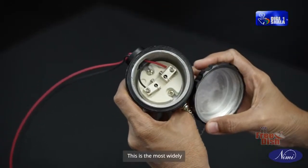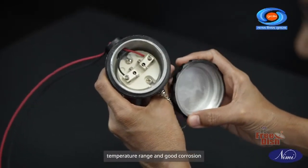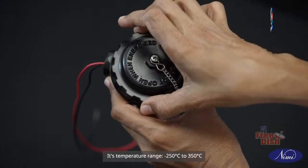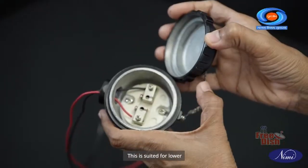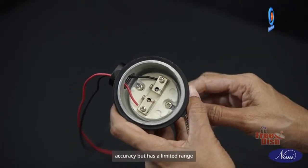This is the most widely used thermocouple due to its wide temperature range and good corrosion resistance. Type T, its temperature ranges from -250 degrees Celsius to 350 degrees Celsius. This is suited for lower temperature applications and offers good accuracy but has a limited range.